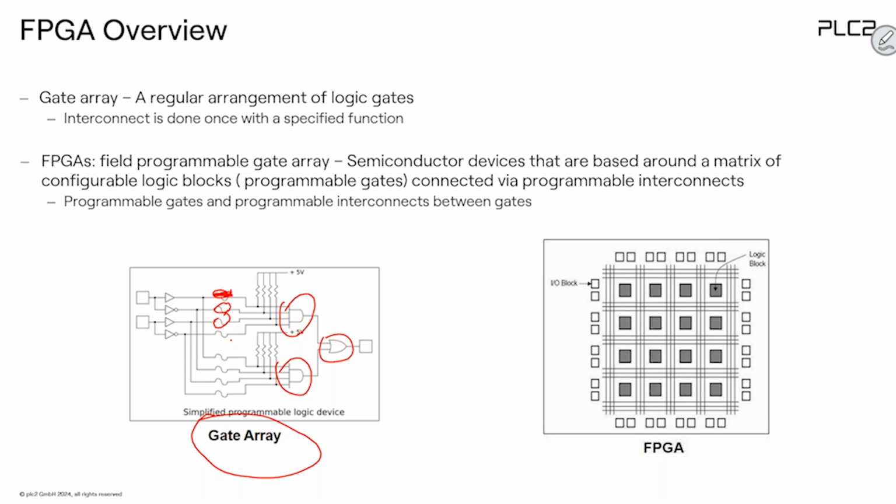Today we're using FPGAs, and that's the idea. An FPGA is a matrix of such blocks. Such a block is called a CLB, which stands for configurable logic block. There could be thousands of such CLBs arranged in a matrix: 20,000, 30,000, 40,000, and so on. This matrix is surrounded by peripheral cells, which are IOs. This could be an input, an output, or bidirectional input and output, meaning bidirectional or tri-state. Depending on the package you select, there could be thousands of peripheral pins connected to the internal matrix.